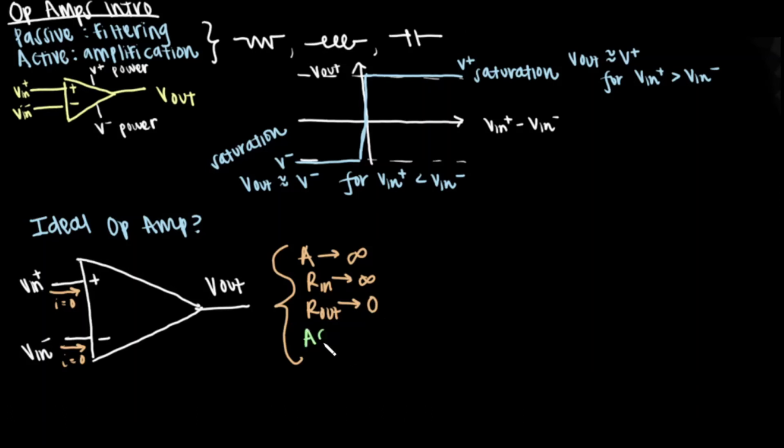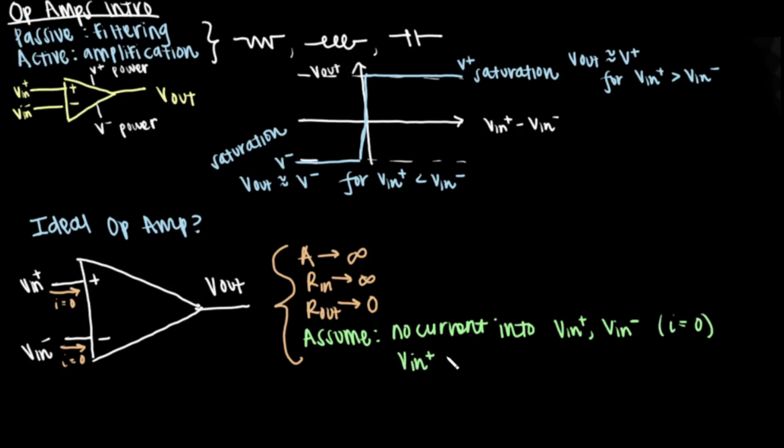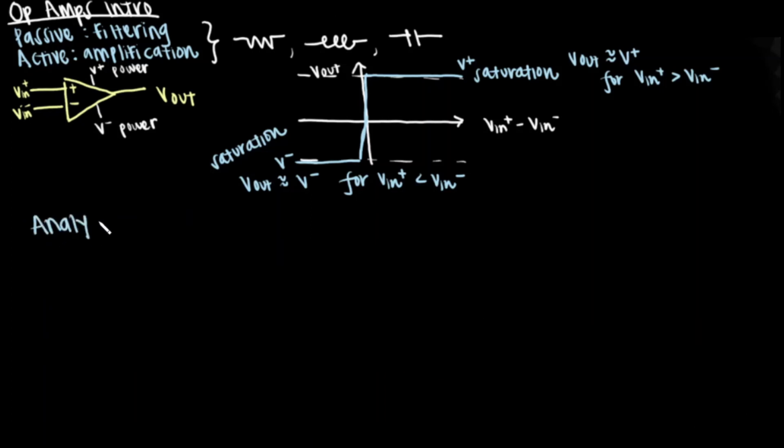In contrast, the active or linear mode of operation of the op-amp is where the differential input is zero and the output is strictly between the rails. In practice, the op-amp reaches that linear range of operation only by providing negative feedback. In the case of zero feedback or positive feedback, the op-amp turns into a comparator or a hysteretic comparator.